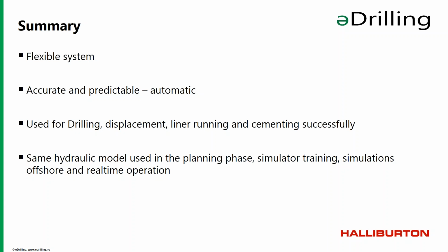As it's automatic, it's accurate, and it's also predictable. The system has been used for drilling 12¼ inch, 8½ inch, 6 inch, and 5¾ inch sections. I've used it for displacement with several fluids, running of liner and cementing, all of them done successfully.